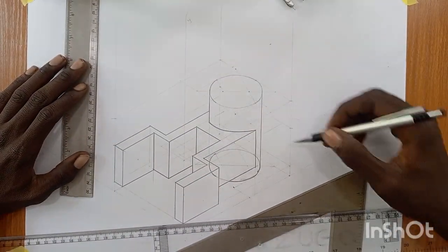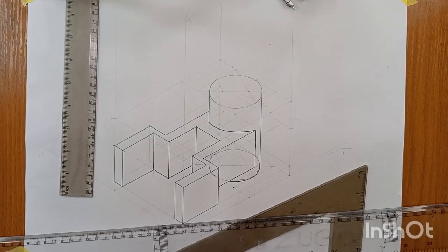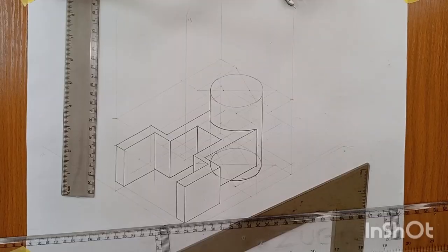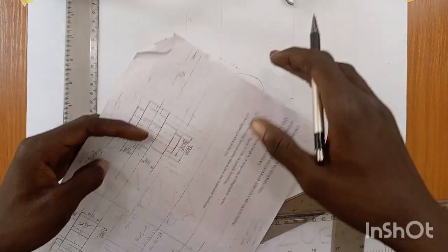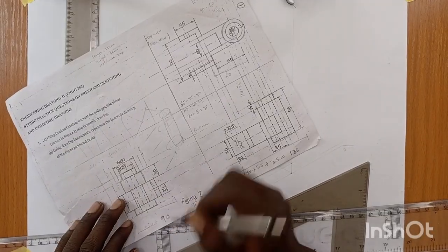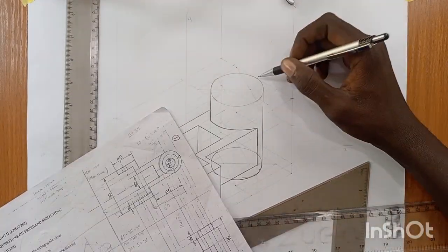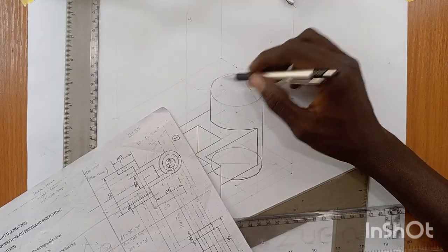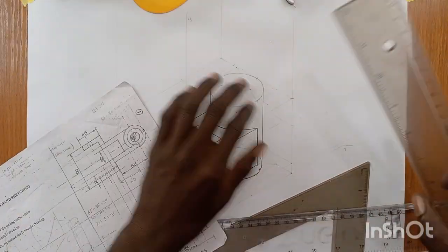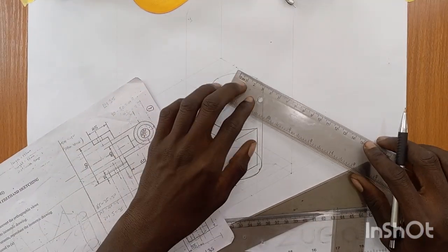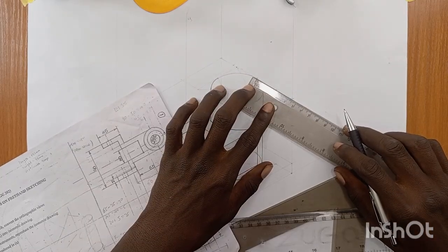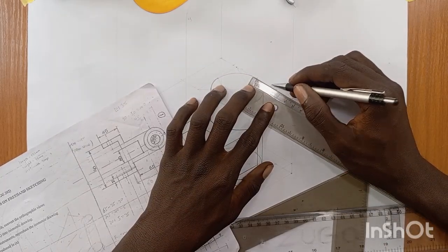Let's draw the base of the smaller cylinder. The base lies at the top of the bigger cylinder. The diameter of the base is given to us as 35, which means 35 by 2 is the radius, which is 17.5, right? So now, this is the half of this, and this is the half of 50, half of this 50 also. And it's at the center of the bigger cylinder. Therefore, I want to draw a 35 diameter line at the center. How do we do so? We take the radius, 17.5, up and down.